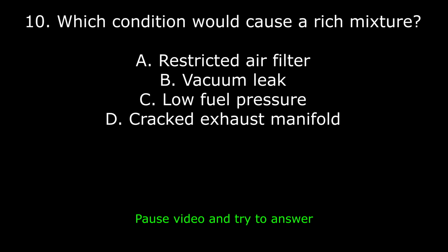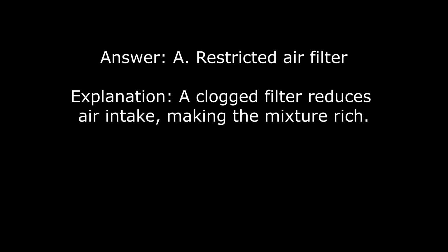10. Which condition would cause a rich mixture? A. Restricted air filter. B. Vacuum leak. C. Low fuel pressure. D. Cracked exhaust manifold. Answer: A. Restricted air filter. Explanation: a clogged filter reduces air intake, making the mixture rich.